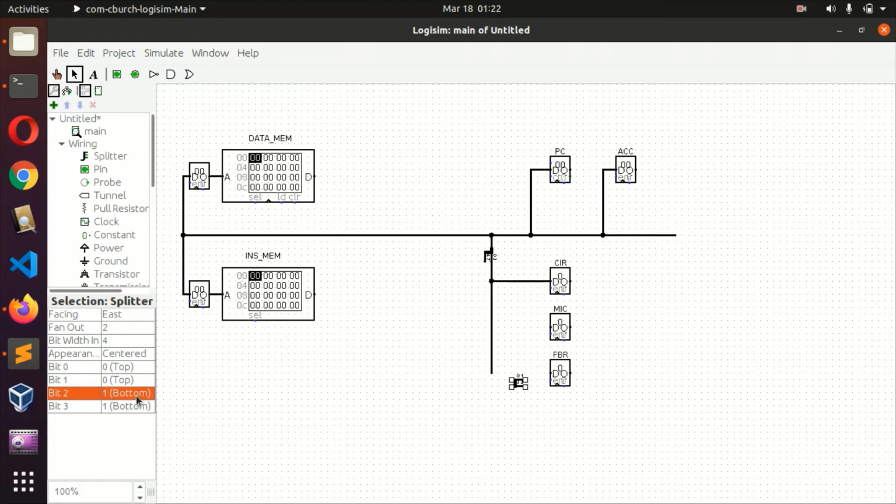So I'm going to change the setting a little bit. You can see what is there, right? So the first 3 low order bits is what we'll take and send it here, and we can just tie the rest of the bits to ground. It won't do anything. We are not using those bits.